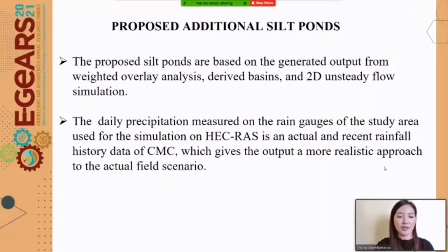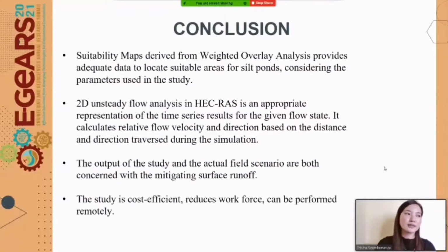the actual field scenario. So our objectives were achieved, so therefore we concluded that suitability maps derived from weighted overlay analysis provide adequate data to locate suitable areas for silt ponds, considering the parameters used in the study. And we also concluded that the 2D unsteady flow analysis in HEC-RAS is an appropriate representation of the time series result for the given flow state.